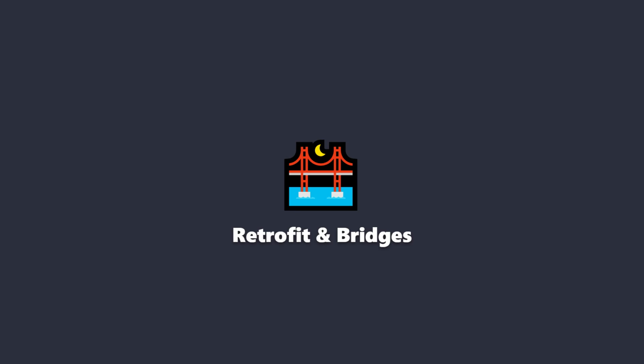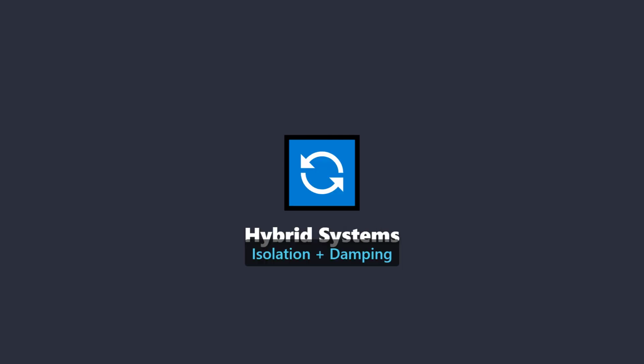Isolation systems drastically reduce floor accelerations throughout the structure, but necessitate large displacement gaps around the building perimeter. Conversely, dampers effectively control interstory drift and reduce shear forces without requiring significant perimeter space. Hybrid systems combine the benefits of isolation bearings with supplemental dampers, achieving optimized performance by balancing period shift, acceleration reduction,